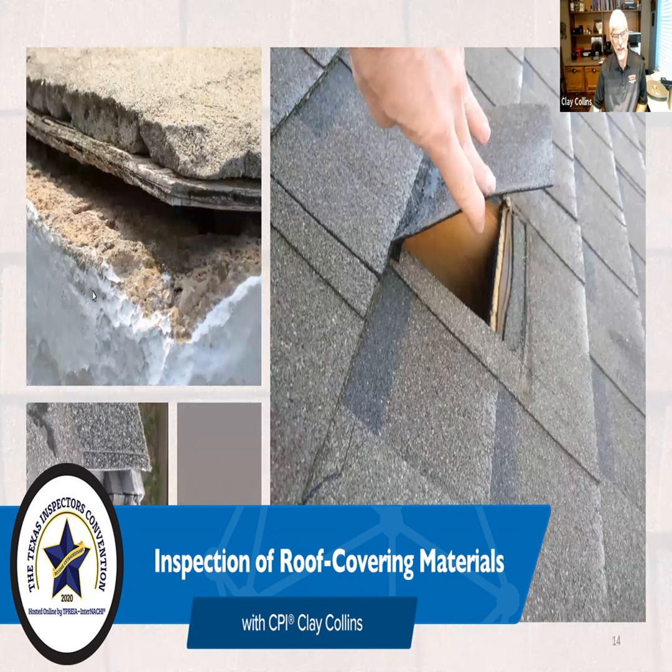And most often I end up describing that as near the end or at the end of its useful life. And without regard to its performance, I don't care if it's leaking or not. The condition of that roof is such that it's going to probably have to be replaced. And keep in mind that on a roof in that condition, the home buyer probably cannot get insurance. So be sure you address that.